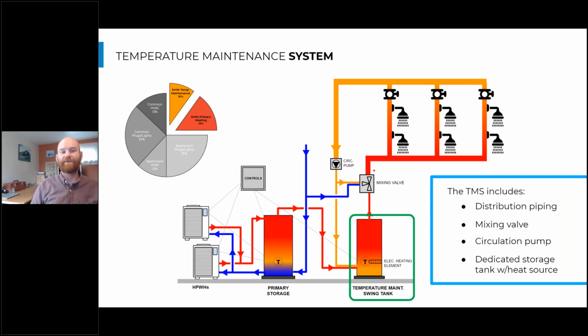But the temperature maintenance, the issue is how large is this distribution piping and how uninsulated is it, or what's the level of insulation? We have a lot of distribution piping and very little insulation. We're going to see a big temperature loss or a high flow rate, and that temperature loss and flow rate will de-stratify our tanks, and so that's where we really have the Achilles heel.